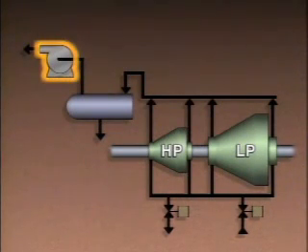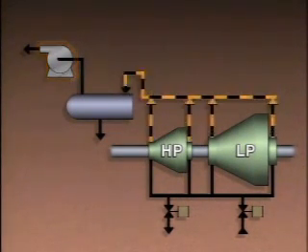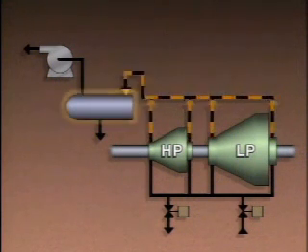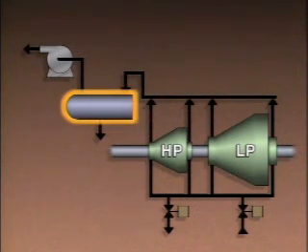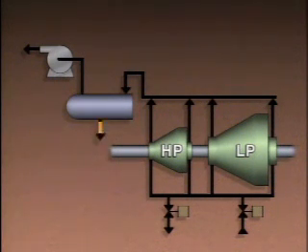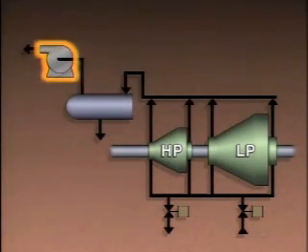An exhauster draws a vacuum on the entire system, pulling air and steam from the glands into the gland steam condenser. In the condenser, steam is condensed, and the condensate is usually drained. Air and any other non-condensable gases are discharged to atmosphere by the exhausters. Normally, the gland steam seal system and the gland steam seal exhaust system work automatically. However, since both your safety and the efficient operation of the turbine unit depend on them, periodic checks are needed.